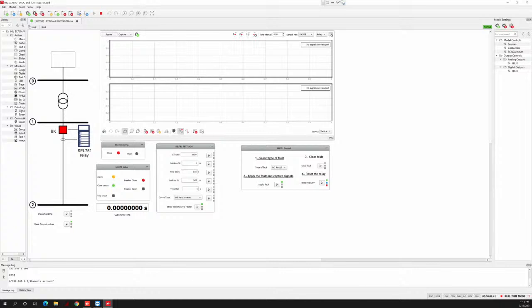For you, probably it's not relevant, because for many years overcurrent has been a local protection. We need to open the circuit breaker when there is too much current. But there are many other protection schemes that are called wide area protection and control. Wide area protection and control means taking measurements in several places. And if you need to take a decision based on several places, you must be sure that everything is happening at the same time. And that is where this clock comes in, okay?